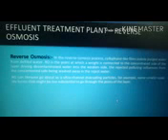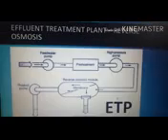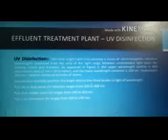UV disinfection. The term ultraviolet light describes a range of electromagnetic radiation, with wavelengths produced from an area of the light range between visible light and X-rays, as shown in the figure. The upper wavelength limit is 400 nanometers. 1 nanometer is equal to 10 to the power of minus 9 meters, and the lower wavelength limit is 100 nanometers. Below 100 nanometers, radiation ionizes practically all atoms.